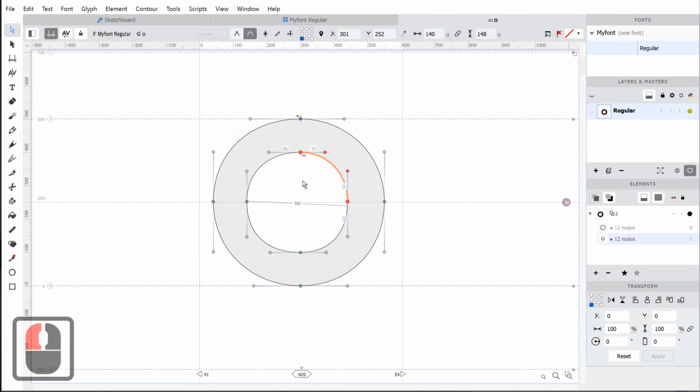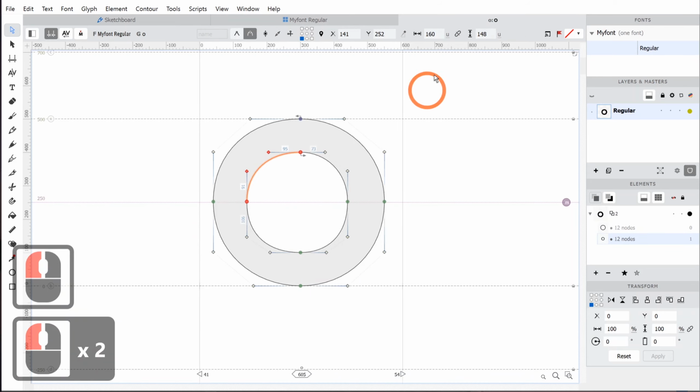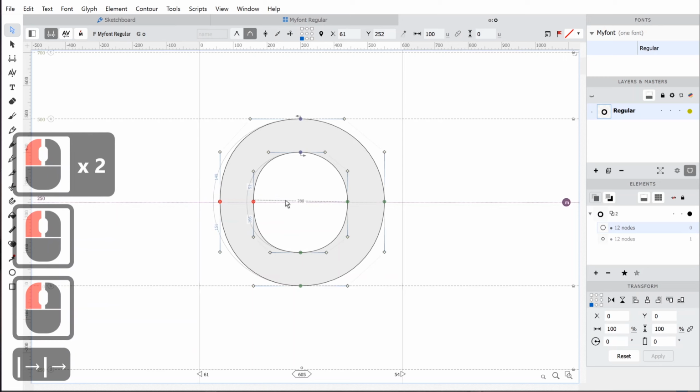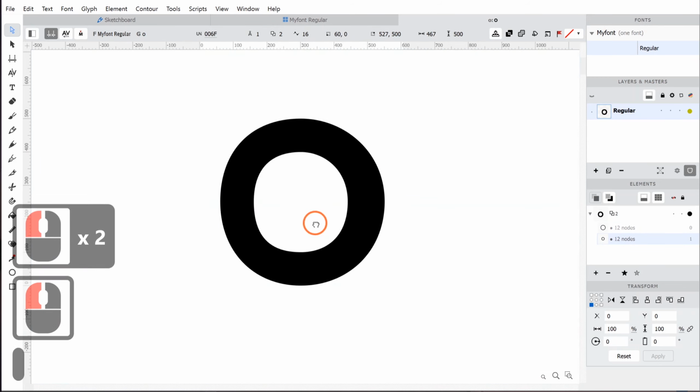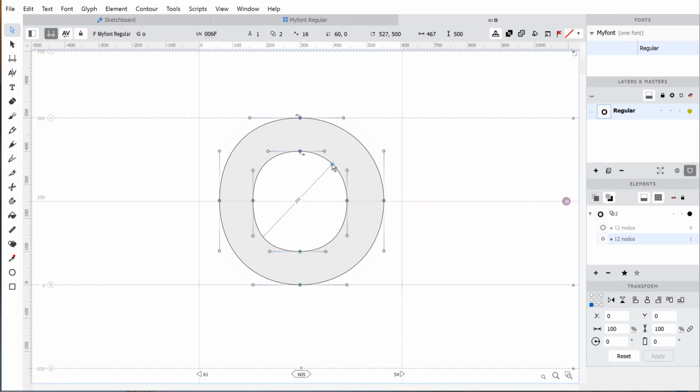Let's learn how to adjust the curve very quickly. You can click and drag on any place of the curve except the anchor point, and you can quickly change the curve. If you want to make smaller changes to the shape like moving anchor point 1 or 2 units, you can do this easily by holding Ctrl and dragging the point. It will make the finer adjustment.